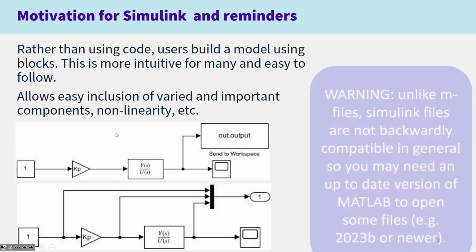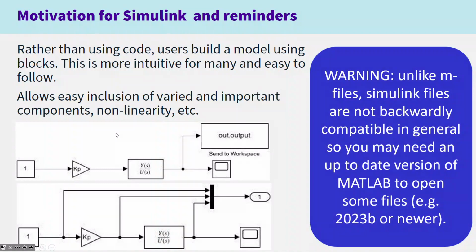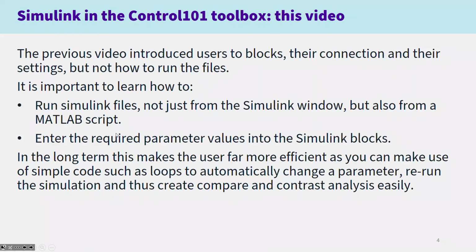Motivation for Simulink then, and some reminders. With Simulink, rather than using code, users can build models using blocks, and this is often more intuitive and easier to do. It also allows the inclusion of varied and important components, nonlinearity, and so forth. But an important warning: unlike with M files, Simulink files are not always backwardly compatible, so you might need an up-to-date version of MATLAB to use some of the files that are in the toolbox. So then, let's get on with this video.